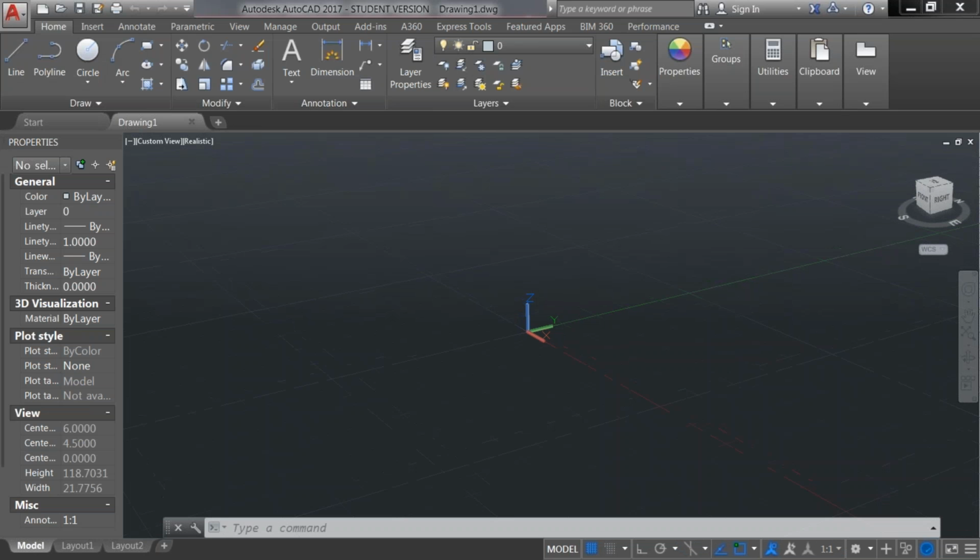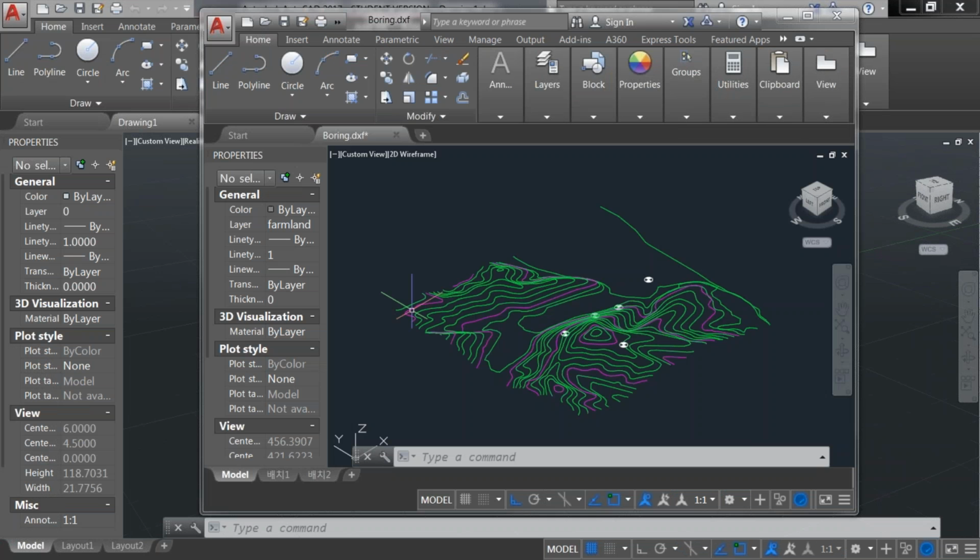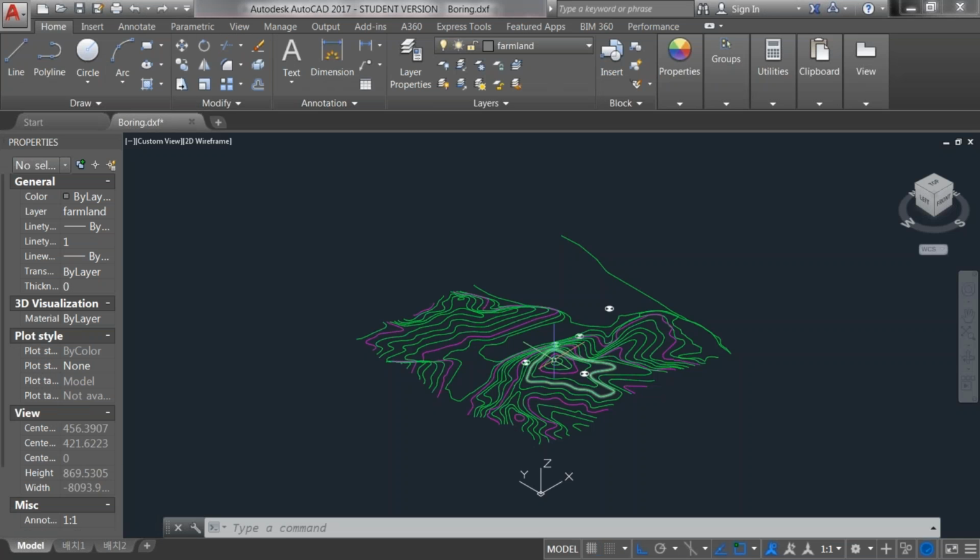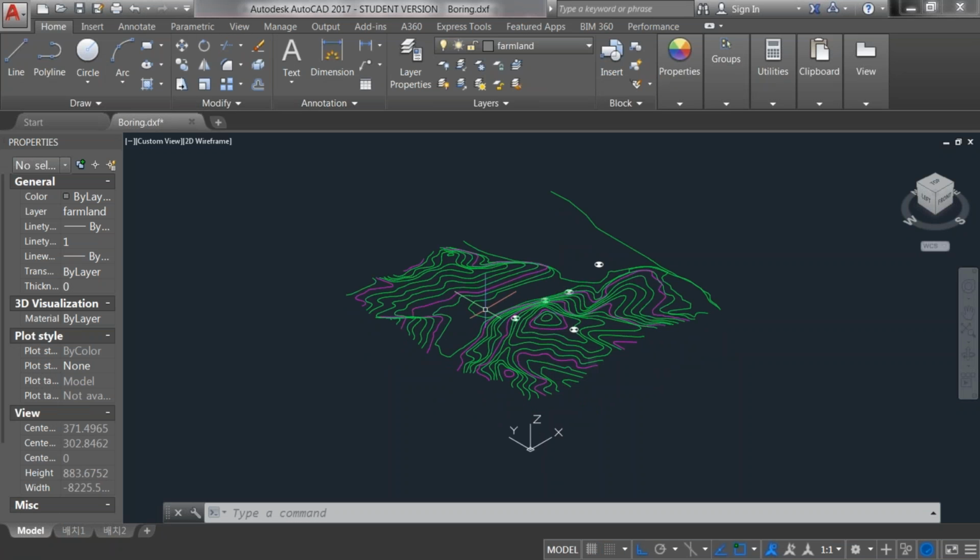Let me open here. So this is the file we're going to import for this first part. You can see that they're just simple contour lines. If I leave my cursor, for instance, this is in one layer called 7111, but it's a polyline. And if I go to another, this pink line, this would be in a different layer, but it's also a polyline. So just keeping track, the program will recognize the different layers and will group them for you accordingly. All that matters is that you're close to the center and that you're using polylines.